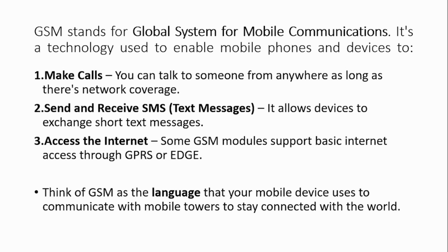It's not English or C programming, but here AT commands are used. These modules are specially designed to understand AT commands, and from the command the module takes the decision: this AT command is to establish a call, this one is to send a message, and this one is to receive a message.